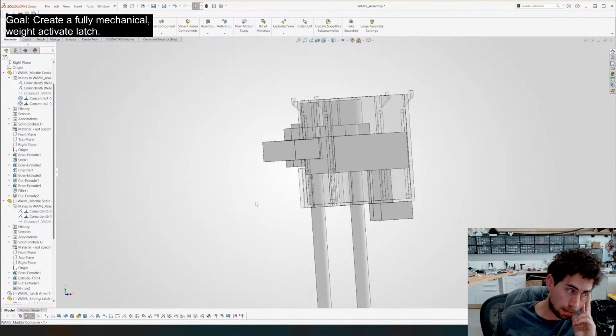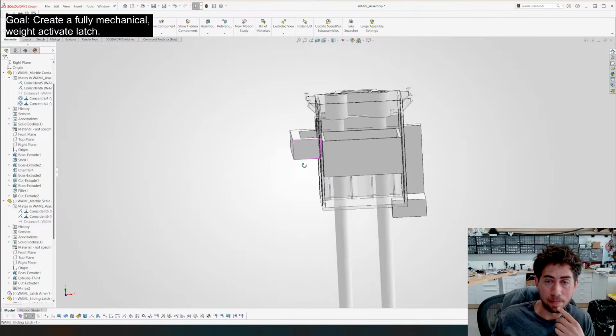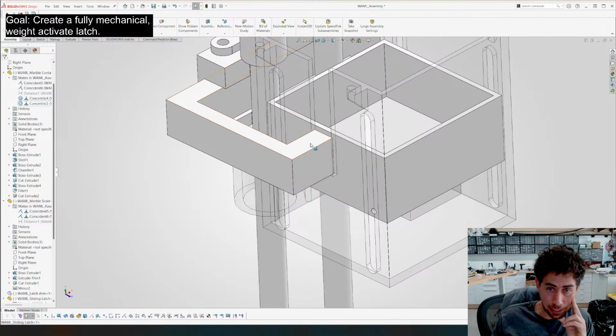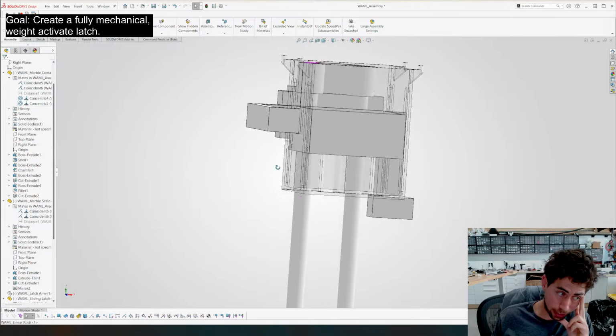I think... change the material to adjust the friction. One thing that I've actually found is PLA on PLA is quite low friction. And then PLA on PLA with WD-40 is extremely low friction. But yeah, ForgeCore is actually very correct on this. If this piece is causing too much of a problem, we put a little bearing in here and it will just roll off. And that would solve that problem. I don't think that we honestly have to worry about that right now.